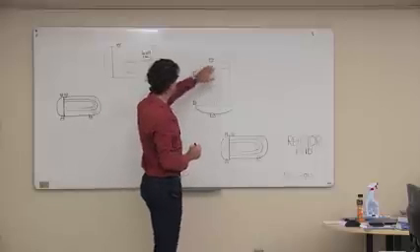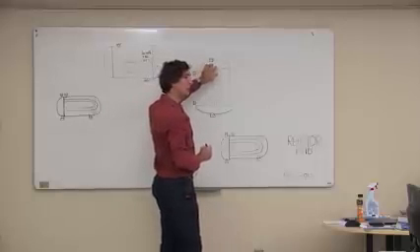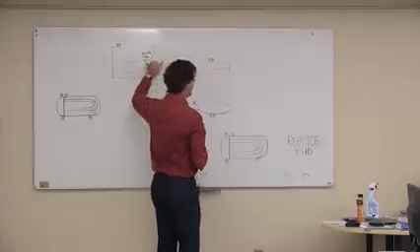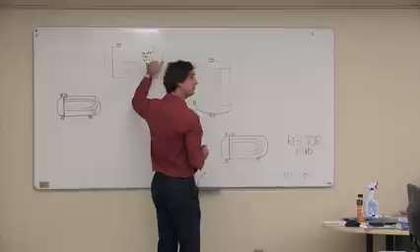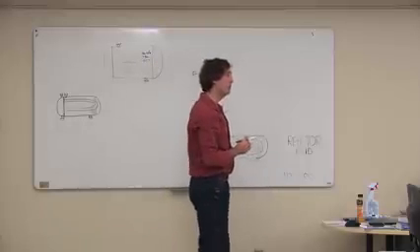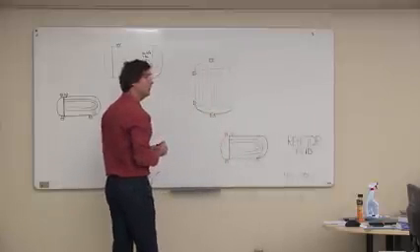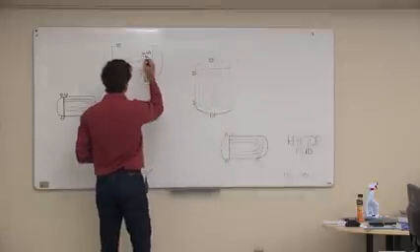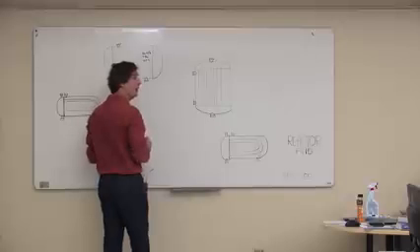So if our process is at 220, that's roughly where our process is in terms of temperature, we're going to be probably a little bit too cold at 165. We probably need to be closer to about 200 degrees Celsius on the steam side, which is going to boost this pressure up to something higher than 7 bar.